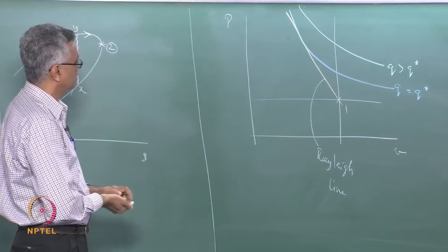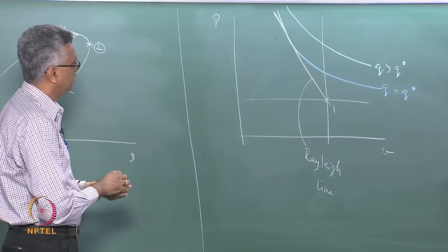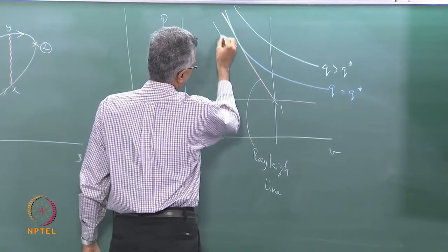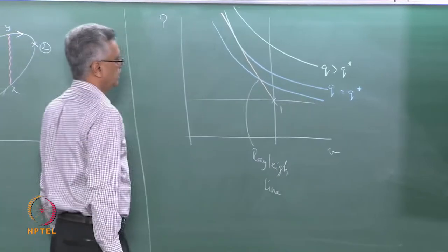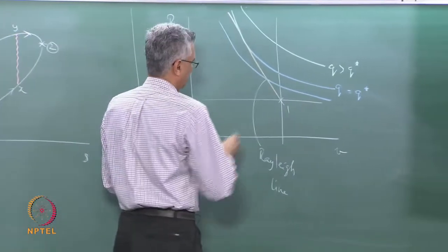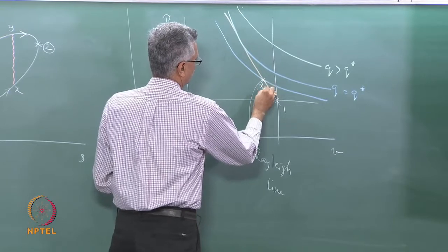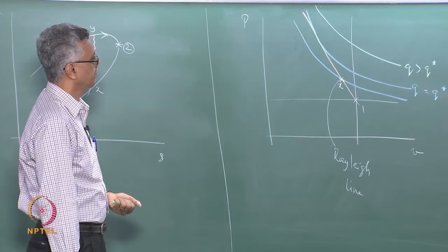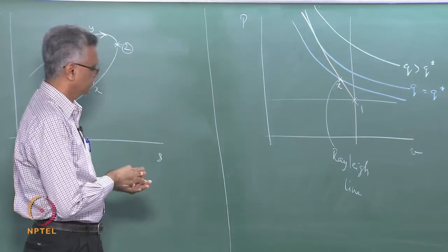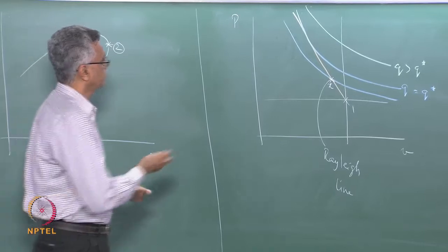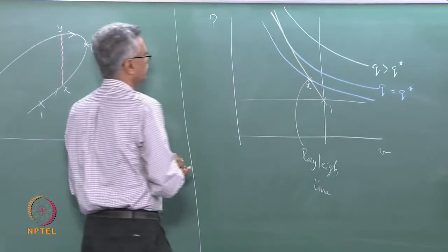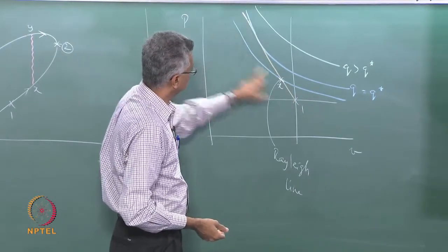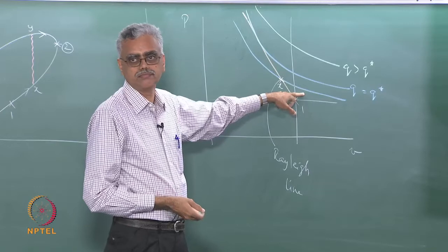So, what actually happens is I travel along the Rayleigh line up to some value of Q. So, this would be my state X. Now, each Rayleigh line intersects an H curve at two locations, okay.